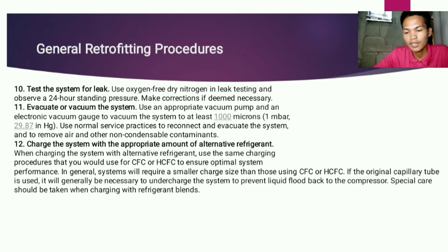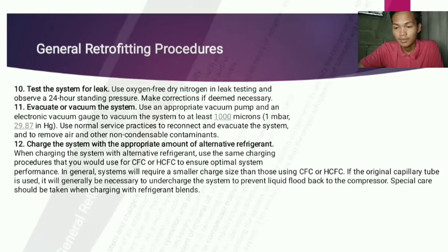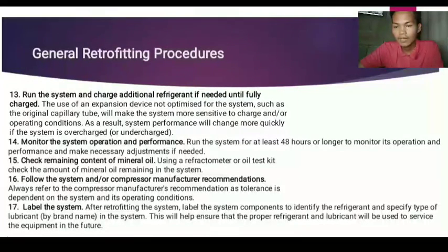Special care should be taken when charging with refrigerant blends. Number 13, run the system and charge additional refrigerant if needed until fully charged. The use of an expansion device not optimized for the system, such as the original capillary tube, will make the system more sensitive to charge and or operating conditions. As a result, system performance will change more quickly if the system is overcharged or undercharged.